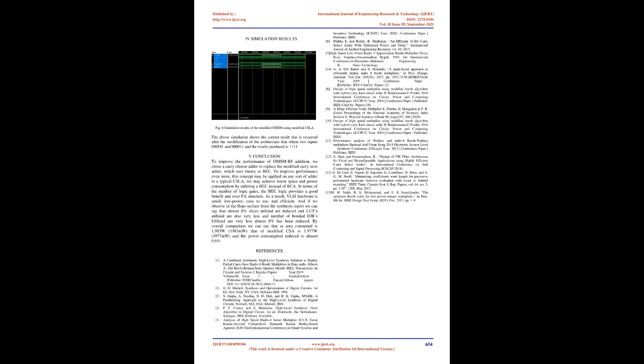The latency of our suggested architecture is only minimally improved since logic circuit processing decreases the number of concurrent paths, and the area efficient carry select adder, on the other hand, uses the same amount of space and power as the classic carry select adder while maintaining the same partly parallel processing architecture.